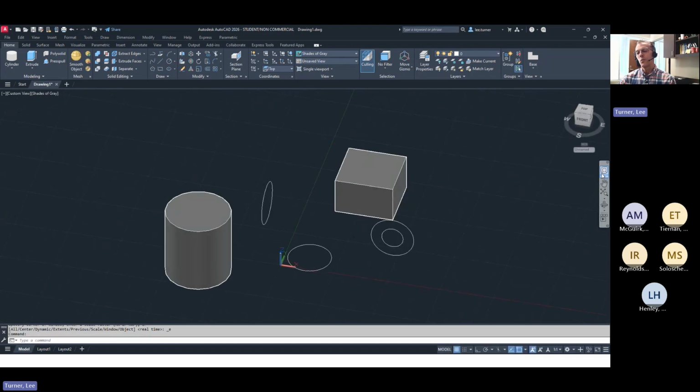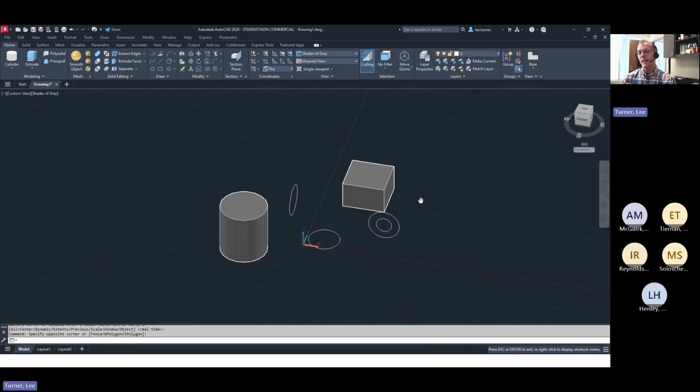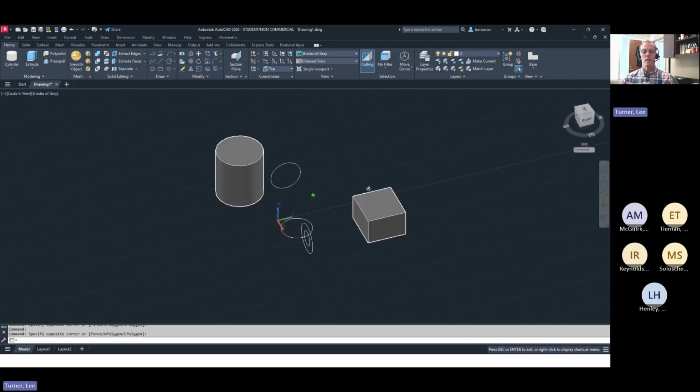You also have some of these tools over here on the right-hand side of the screen. Here you have zoom extents. If you click the down arrow, you've got a ton of different zoom options that you can play with as well. But we've been using the middle mouse button a lot by zooming in and out. You can also see right below or above it, you can see the pan, or you can click on this lower one. There's your free orbit or continuous orbit, but they're readily available with the shift button and then the middle mouse button if you want to do that, okay?